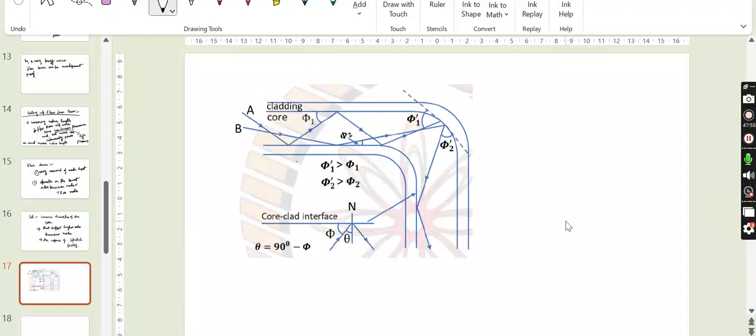has been to exploit the bending loss of a fiber to an advantage and subdue the higher order modes. As we know, light passes through the straight core without any leakage because it strikes the cladding-core interface at an angle greater than the critical angle. However, when the fiber is bent, a part of the light will inevitably strike the interface at an angle lower than the critical angle and will escape as it travels down the core.